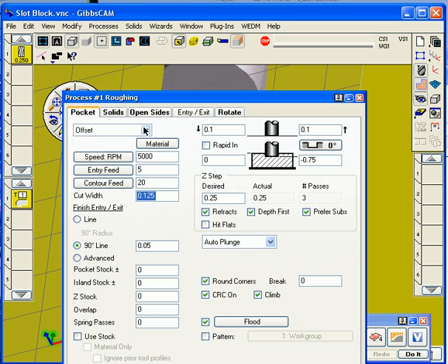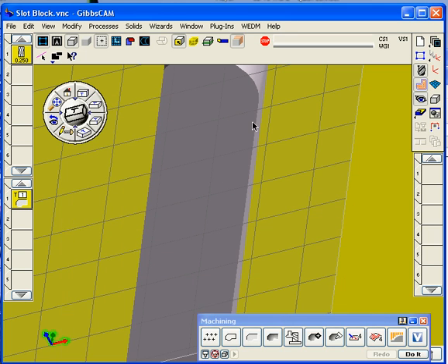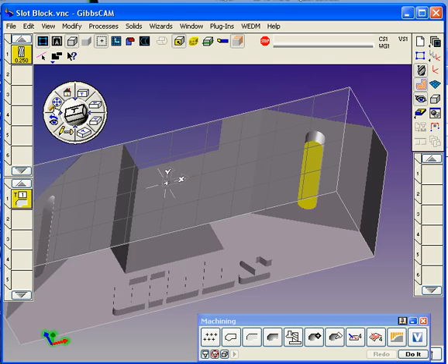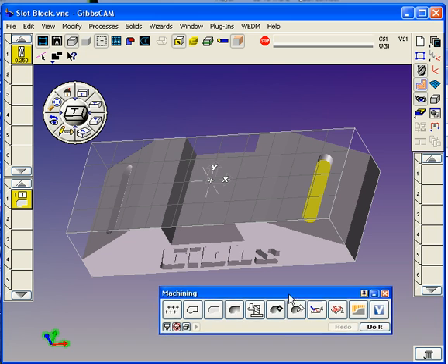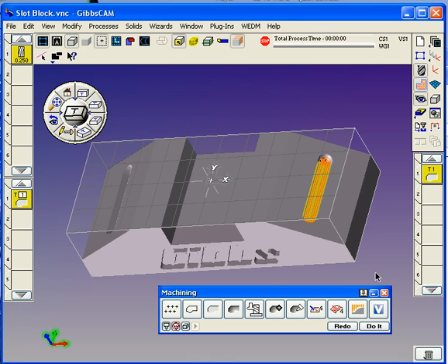We're going to use the offset contour, the offset pocket thing here, and all you really need to do is click the face of that part. Do an unzoom here so you can see what we're doing. All I did was select the bottom of that part there. The Do It button turns black, and we've machined that pocket.